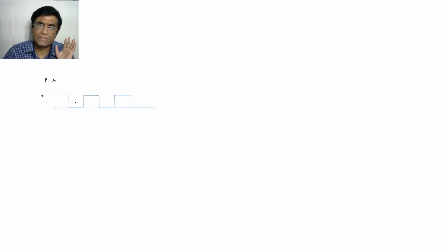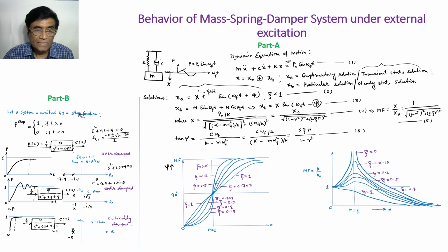All three conditions are stable, but the desirable one is critically damped because it is very quick, and the response of the controller will be much faster. If you can design gain parameters and so on considering a critically damped condition, then the controller will be much better.